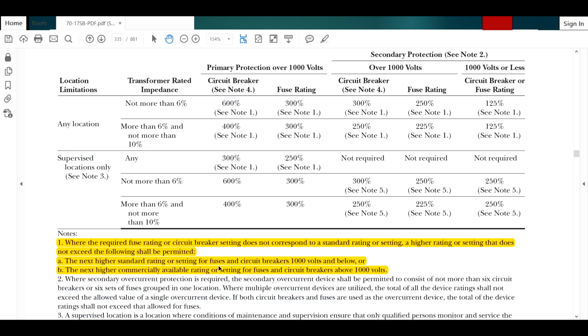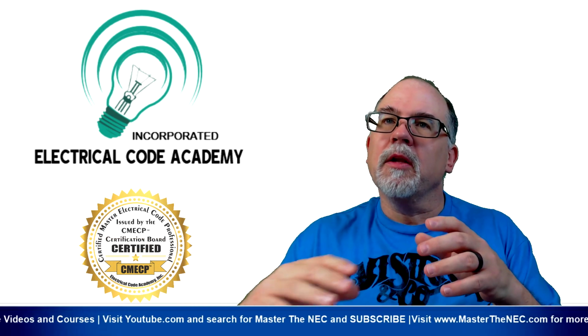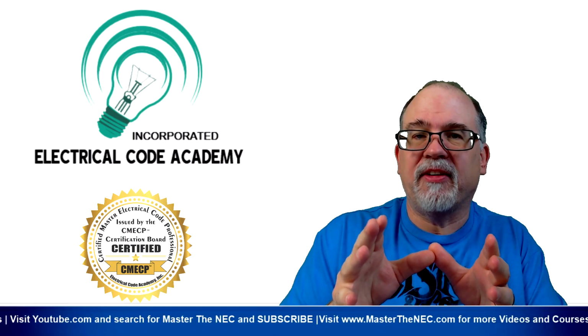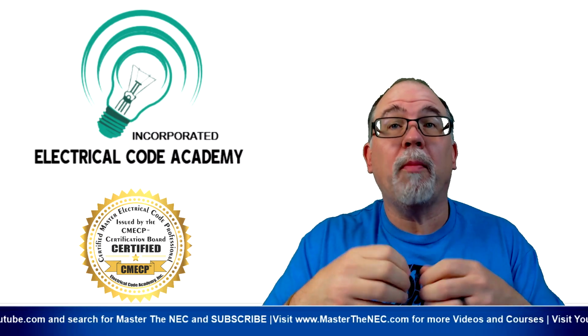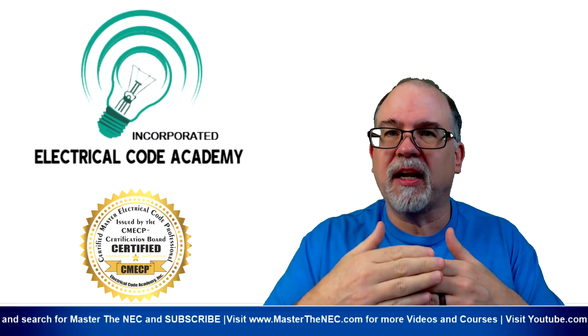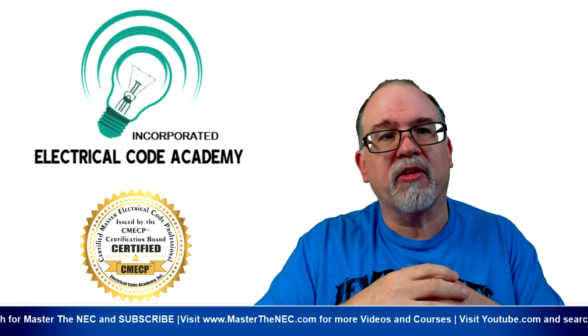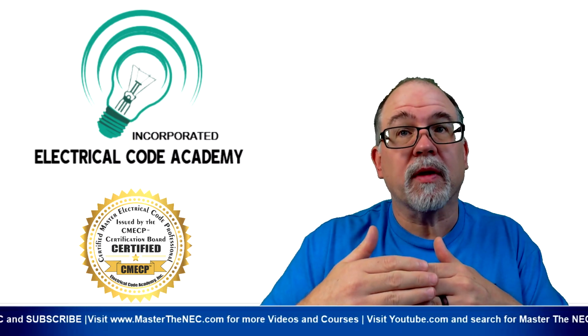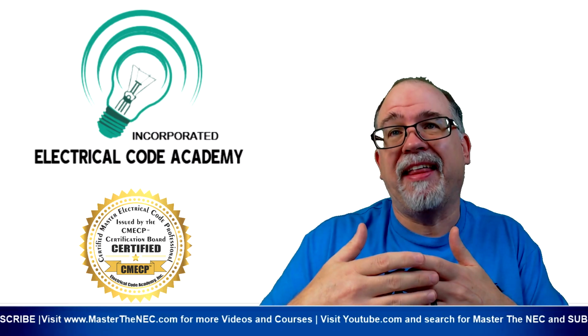Okay, so that's what it means here. Now, what about the B? B says, well, the next higher commercially available rating or setting for a fuse or circuit breaker above 1,000 volts. So what does that really mean? Well, the standard ratings are what's put in Table 240.6(A) of the NEC, but a lot of the manufacturers will make specific commercially available step sizes of circuit breakers. And so you would go to the next available one, okay? And that's how that would apply there, all right?